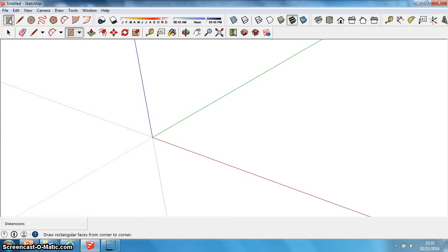I'm going to click on the rectangle tool, and I'm going to draw a very quick rectangle. Now the first thing you should know is what I'm going to do is I'm going to click once on the mouse and release, and then I'm going to move away so it starts to draw the square. Okay, and you should notice in this dimensions box that numbers start to appear. So here we go, click once, release, and move away. So I'm not holding the mouse button right now, and as you can see the dimensions on the bottom of my screen just here, jumping up and down.